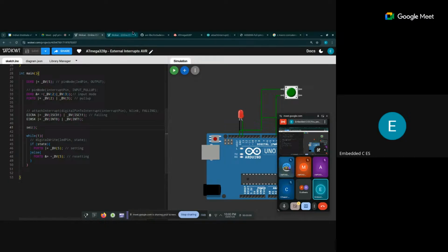So there will be a register. So with one bit, so there are many interrupts, right? You can enable and disable these interrupts globally, like to stop all the interrupts for a certain period of time, from triggering any interrupts. You can think of it like that. SEI will enable all the interrupts. If I do the reset, that will reset that bit, so no interrupts will get triggered.